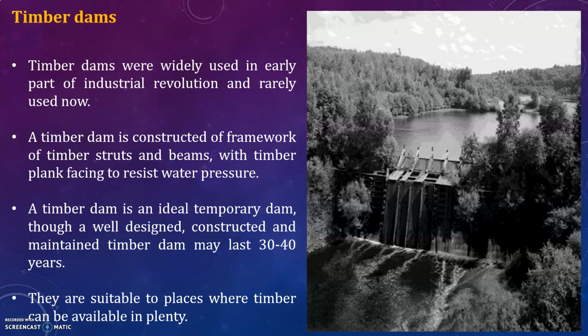So let us discuss some of the advantages of timber dams. It is of low initial cost, suitable for any type of foundations. Where only temporary dams are to be constructed, timber dams are more suitable. Greater speed in construction can be achieved. And disadvantages are high maintenance cost, short life, suitable only for small heights, and greater seepage loss through the body of the dam. These are some of the disadvantages of timber dams.